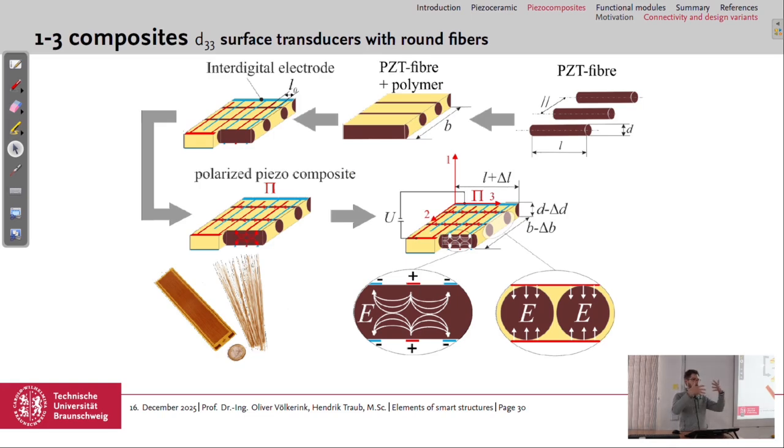So you have one electrode and another electrode, which are then called interdigital electrodes. With this, you can apply a field in this direction, because if we look from this side, the field goes from this electrode to this, from this to this, and the same for the bottom. So we have a field more or less in this direction in the middle.